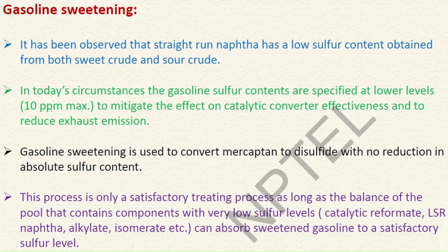So we need to either remove them, or convert them into some other sulfur containing chemical by some chemical reaction, so that the foul smelling mercaptan is converted into a sweet smelling compound, here basically disulfide.